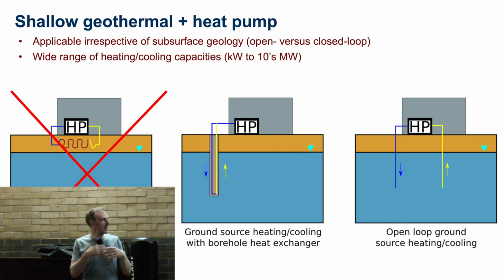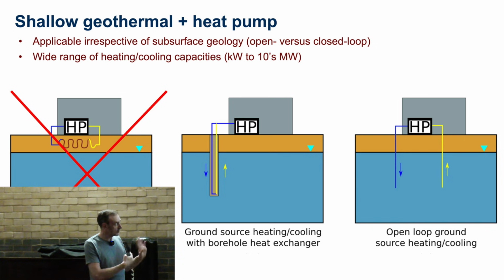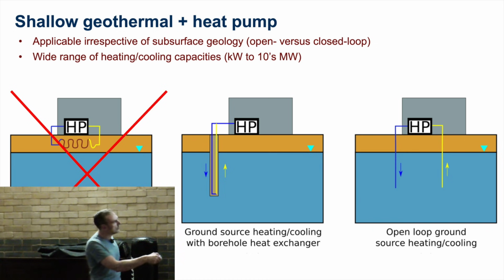In fact, there are even now companies looking into doing this where you would drill some boreholes on your street and they would basically come and sell you heat as a service rather than the fuel to generate your own heat. They would then pipe to you groundwater or some other working fluid that would provide you with this feedstock that you could then boost with your own heat pump. Again, we can do this either with a closed loop borehole, where the fluids remain within the borehole itself, there's no exchange, or we can do it open loop, where we actually produce groundwater.